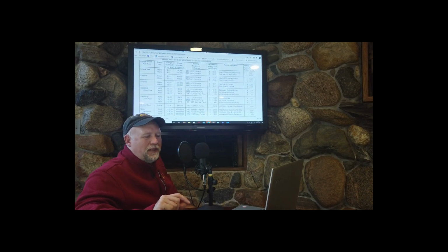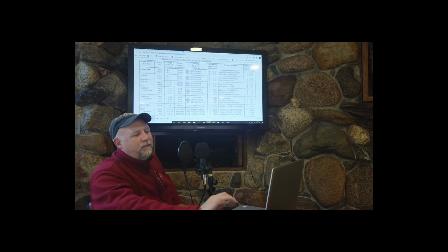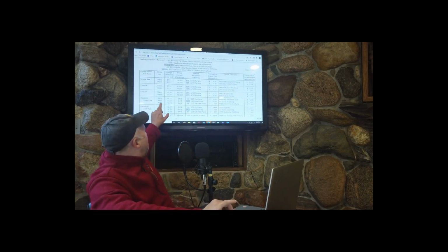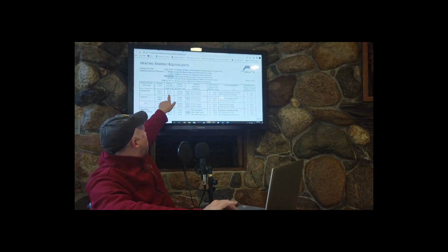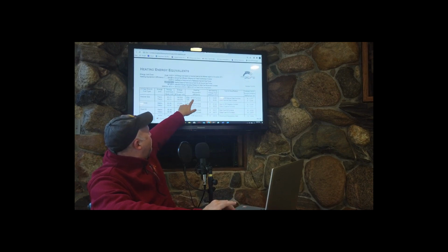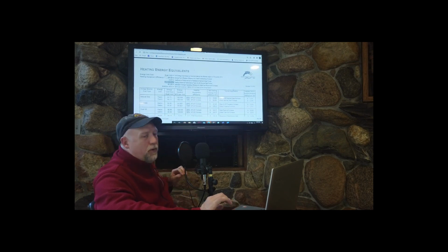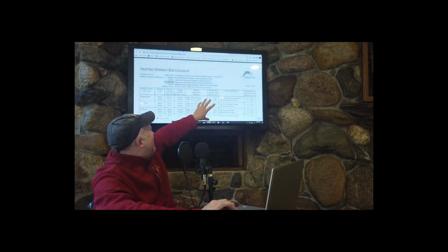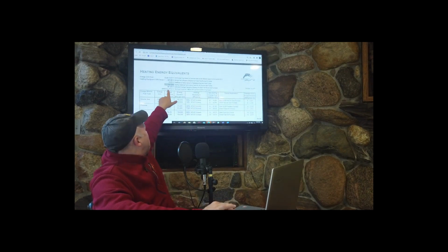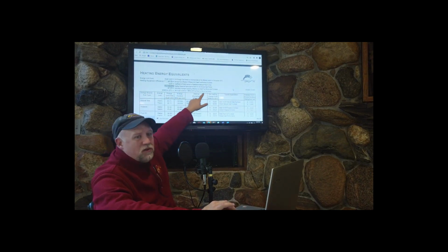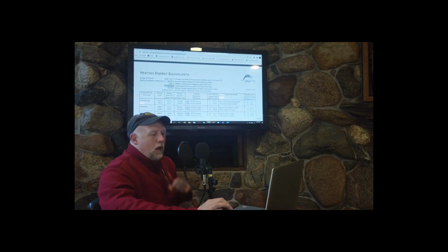Availability can change demand, but so can other external factors like government regulation and public opinion. So let's take a look at each one of these. Natural gas at $1.71 a therm, a 92% efficient furnace, it'll cost you $18.59 per million BTU. That is million BTU in the house, in the living space. Here, notice this: net cost delivered to the living space.